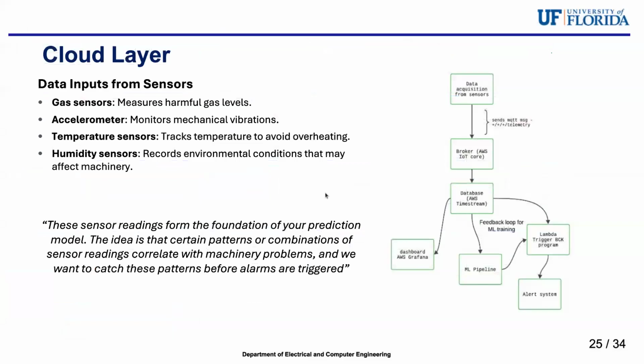In order to give the overlook on the sensor information that we are taking, we have gas sensor information, accelerometers, and a few other environmental sensors like humidity sensor, gas resistance, indoor air quality sensors. All this information collectively helps us to understand the machine condition, so we are able to predict the machine state, like whether it is in normal working condition or is in breakdown or about to break down, so we could send an alarm to the user.